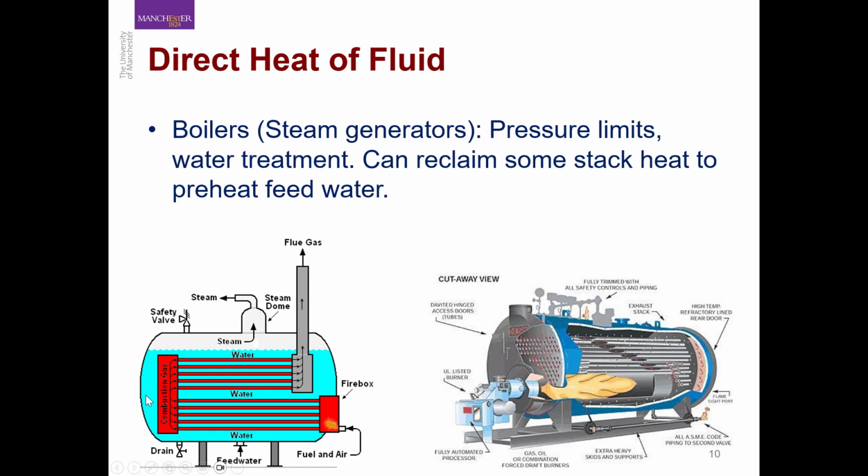Like for example, you want to preheat the boiler feed water, or you want to create low level saturated steam. So as such you are providing heat from this tube directly to the water, and as such you are producing low pressure steam. Another view of the same boiler system. Here you have the firebox, and you can see clearly how the flame would be inside the tube. Then you have several of these tubes, and these tubes are actually heating the fluid around these tubes in the shell.